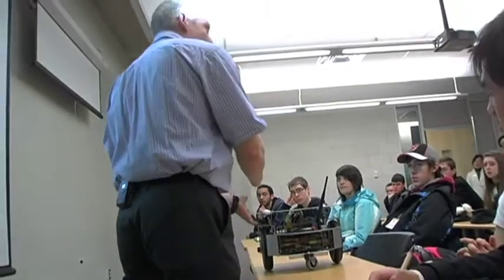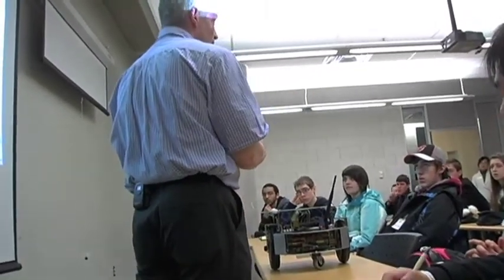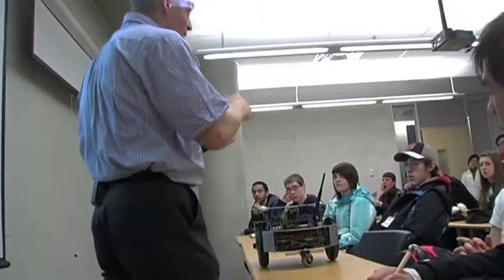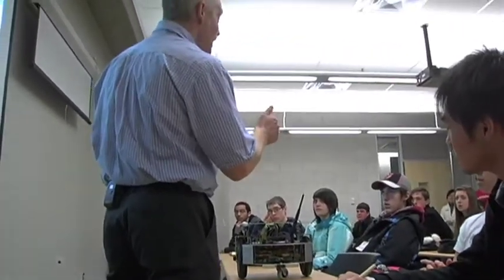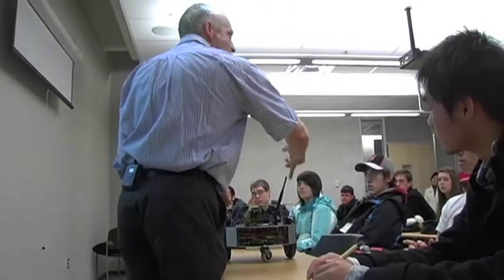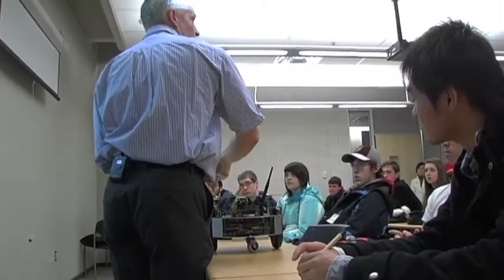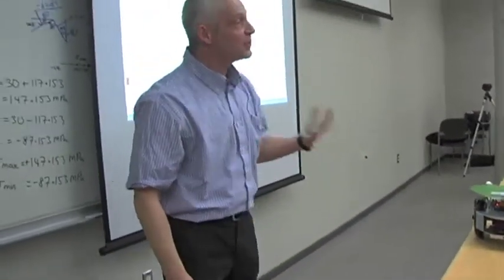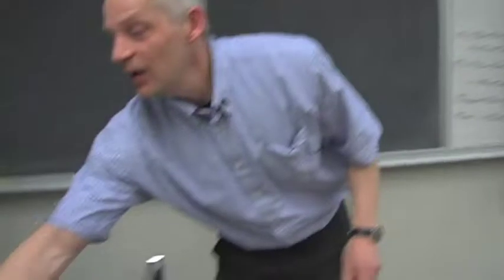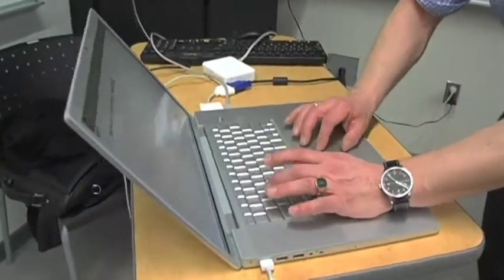So the first thing, I have one motor. I say I want it to run at a certain speed. If it's running faster than the speed I want, I make it slower. If it's slower, I make it faster. And then I take the other motor and match its speed with this motor. This happens about 60 times per second. So this brings us to the other idea of control. The problem is I'm running out of time.